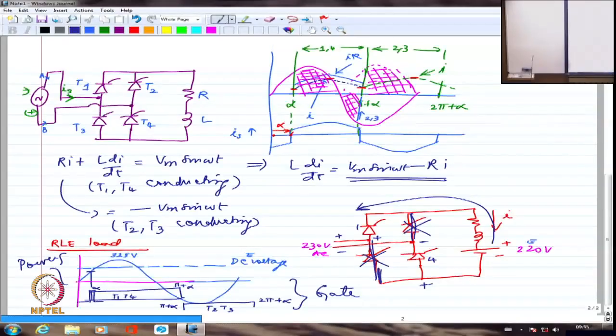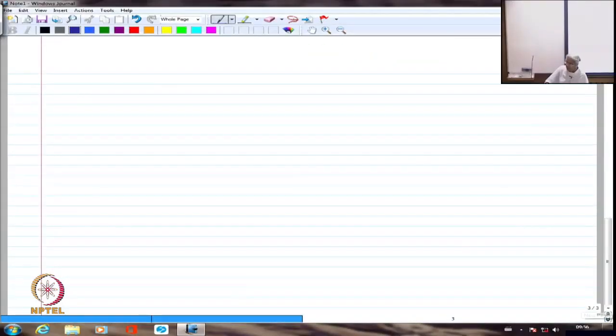But if I give a wider pulse directly, because that is the norm for the thyristor normally, if you may recall, we had said that the pulse has to be given basically to an amplifier. In the amplifier, I had given a pulse transformer in the primary, which is connected to the amplifier, and the secondary was directly connected through a diode to the gate and cathode.